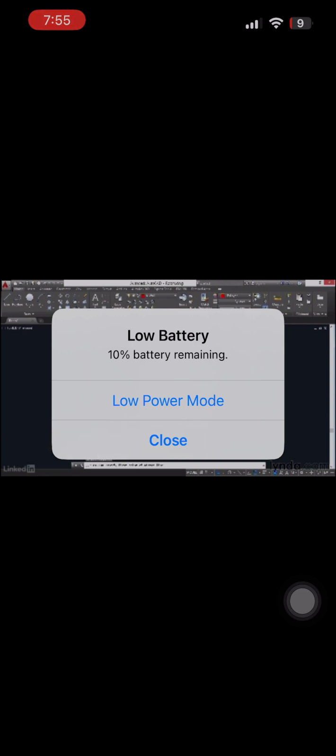Press Enter. Now it says specify first point of mirror line. Basically, we're going to draw this mirror line, which will act as the axis that we will reflect everything through. So click an arbitrary point over here somewhere and see what's happening. Look, the mirror line is shown with a dashed yellow, and if I rotate that, you're seeing that all of the selected objects are reflected through that axis onto the other side.